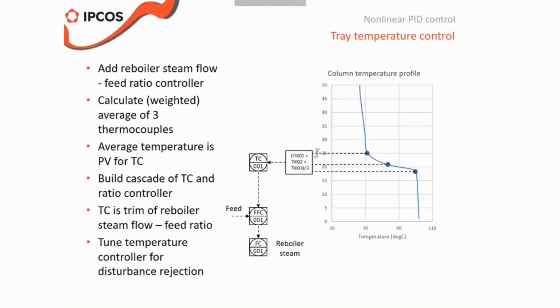And for all these control schemes, it's better to have something simple, which might not be perfect, but have something simple in a DCS, which already helps a lot, instead of including something very complicated, because it's not easy to get it working, and working also when, for example, an upset happens. You have to make sure that these controllers will be able to handle upsets, and the best way to do that is by keeping it simple in the DCS. So the short answer would be yes, it still helps to have a characterization block, and just make sure that the tuning of the quality controller is such that it can handle these flow changes. Yeah, okay, so make it very robust.